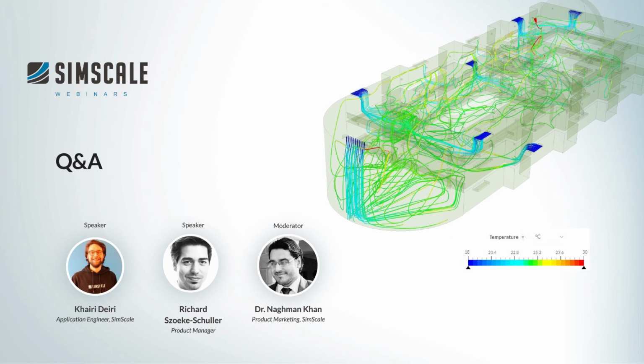So that's the difference. And the combination of tools is typically used where we use the results of one to feed it into the other tool. For example, what you can use SimScale for is you get the accurate representation of the pressure coefficients on the building facade. That takes into account the actual surrounding buildings as well, as they have a large influence sometimes on the actual pressure coefficients of your building of interest. And then you take these pressure coefficients to feed them into your building energy modeling tool, where you can then assess the natural ventilation capacity over the year and if natural ventilation is a feasible strategy for your design.